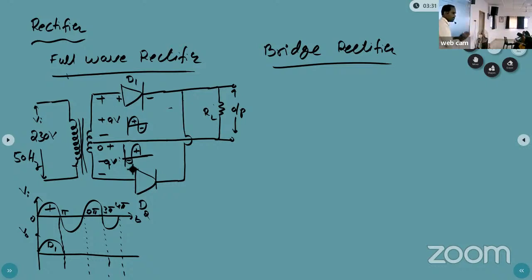So now the first half cycle is over. Now coming to the second half. What is the second half, negative or positive? Negative. So negative voltage will connect to the D1 diode. What will happen? D1 is reverse bias, off. Next, coming to the same duration, D2 diode positive. So the D2 can conduct, short circuit.